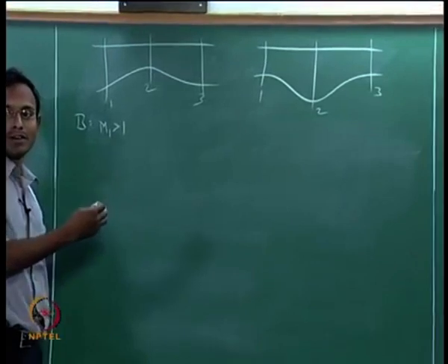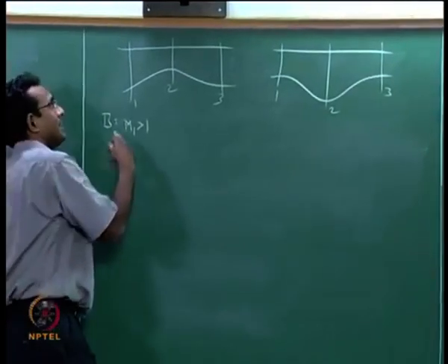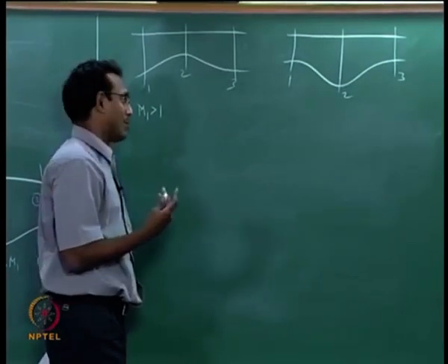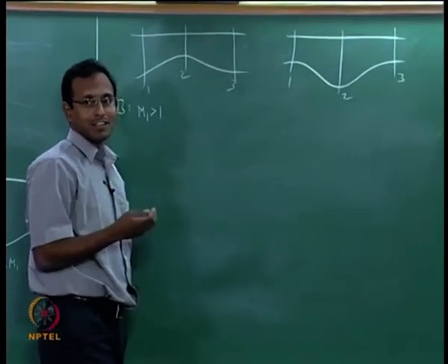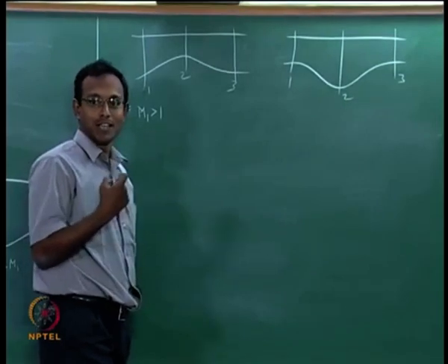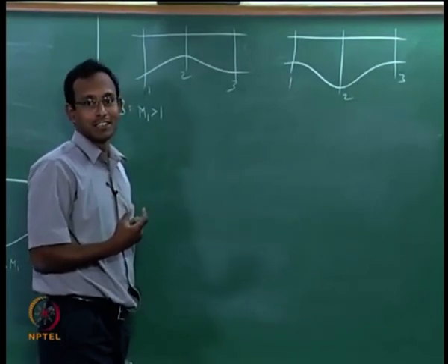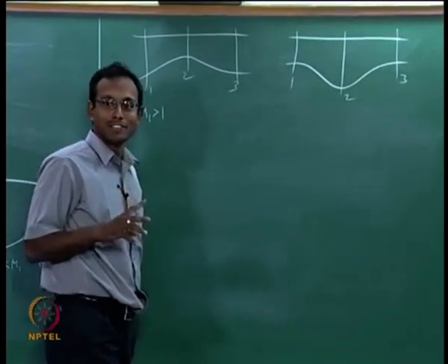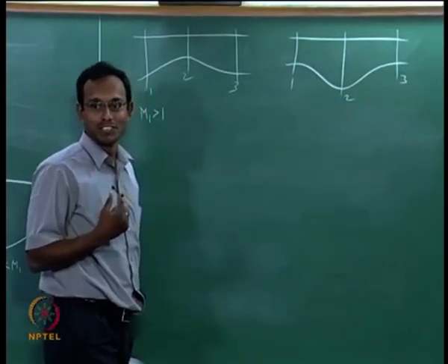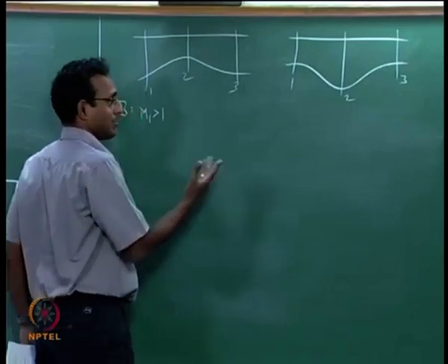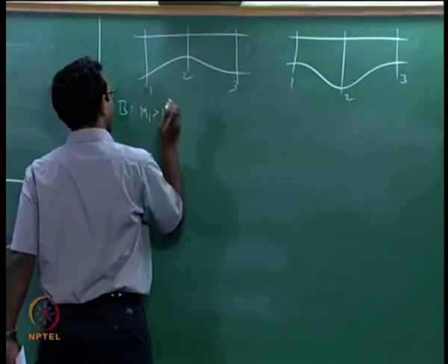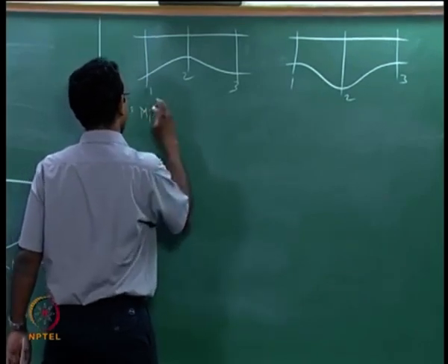If we look at the table, it is going to go in the direction of Mach number equal to 1. By the way, a simple thing: if it is a converging duct, it is going to go towards M equal to 1. If it is a diverging duct, it is going to go away from M equal to 1. But this may get confusing after some time. If you do not remember which is towards and which is away, you will get confused. Instead remember the other statement also. I like this statement anyway, you have to get used to something in your compressible flows.